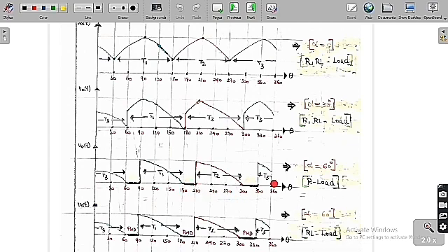Similarly for T3, when T3 is on, V0 is equal to Vcn. Here we are going to follow Vcn, but Vcn is negative. If Vcn is negative, then the current is also negative, and thyristor current cannot be in the negative direction. Because of that, everyone is open in this period. So from 180 to 210, 300 to 330, and 60 to 90, every thyristor is open.